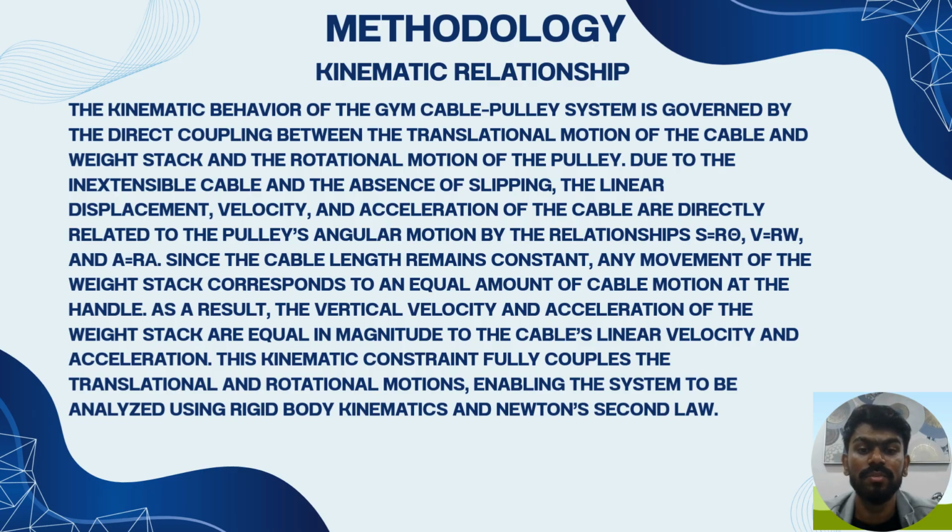Since the cable length remains constant, any movement of the weight stack corresponds to an equal amount of cable motion at the handle. As a result, the vertical velocity and acceleration of the weight stack are equal in magnitude to the cable's linear velocity and acceleration. This kinematic constraint fully couples the translational and rotational motions, enabling the system to be analyzed using rigid body kinematics and Newton's second law.